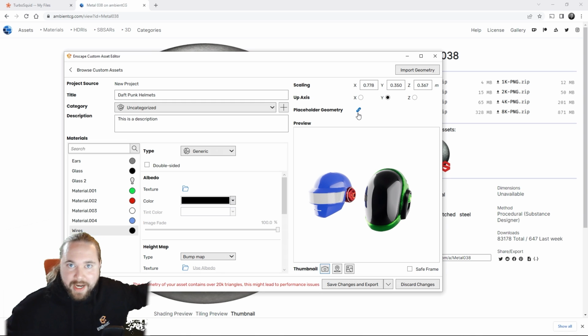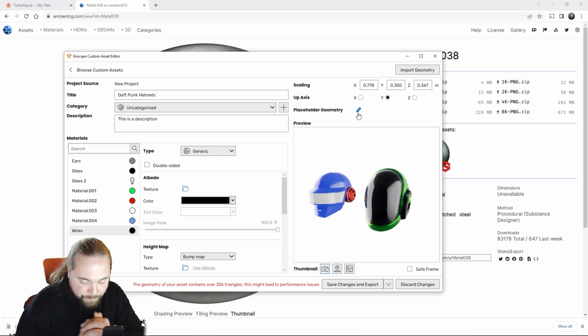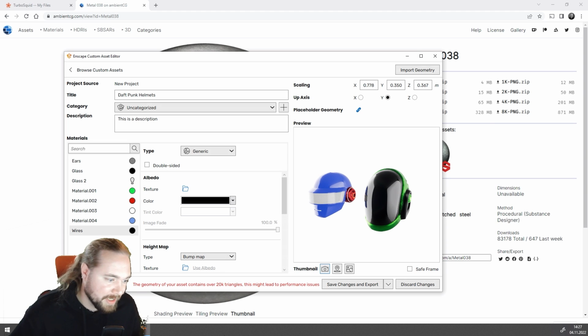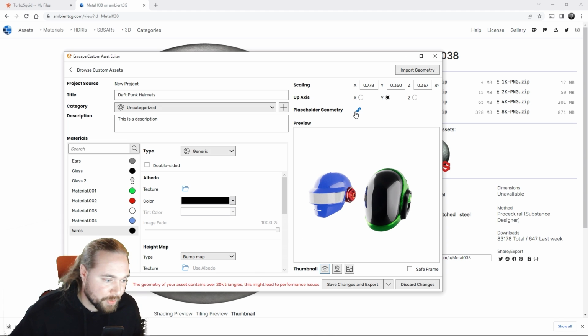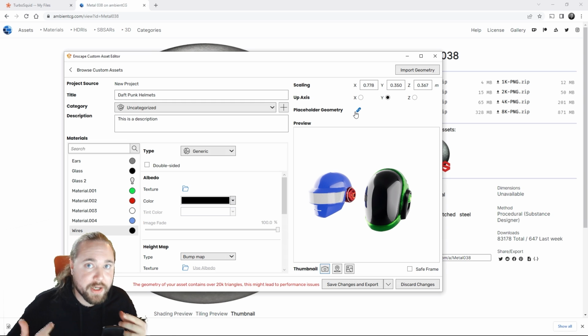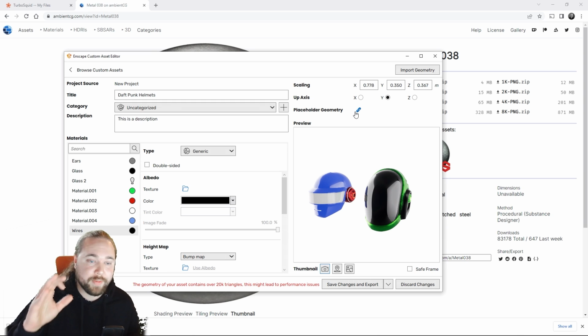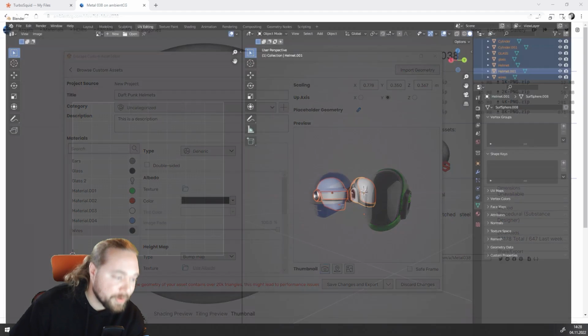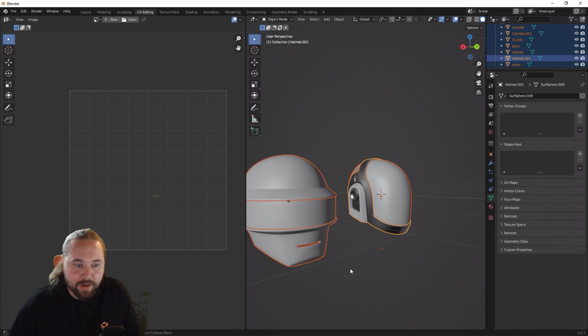And the model that shows up in Enscape is a different one. So that's going to drag down the performance of your design application, the place where you work, essentially. And you don't want that. So you want to make sure you either go with a box, which is being created by Enscape automatically, or you go with a really, really simple model to maintain performance in your native design application. How can we do that? There are two ways we can go by.